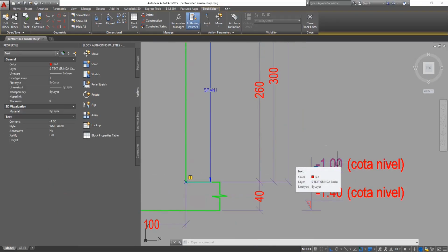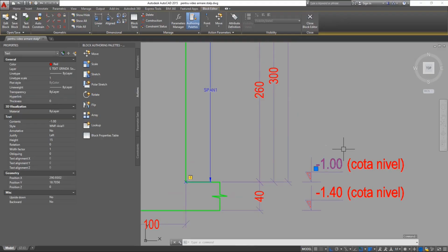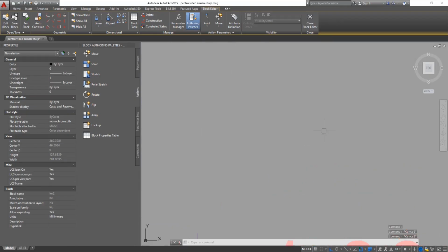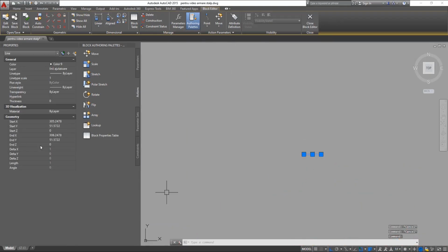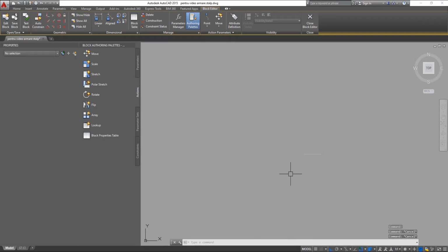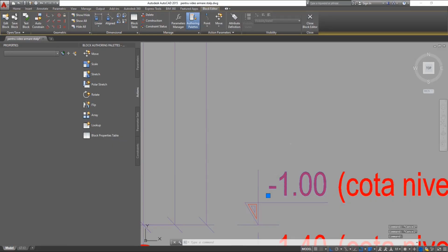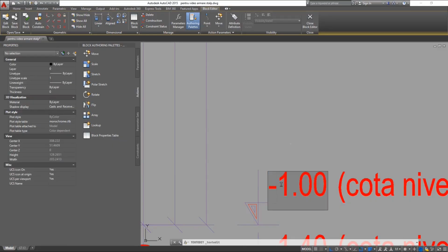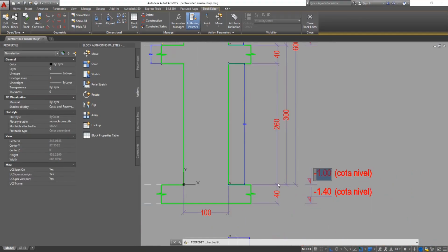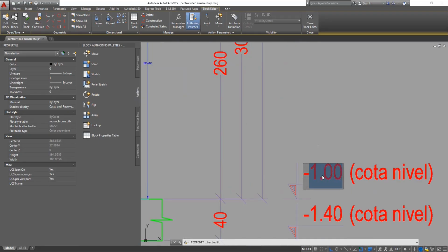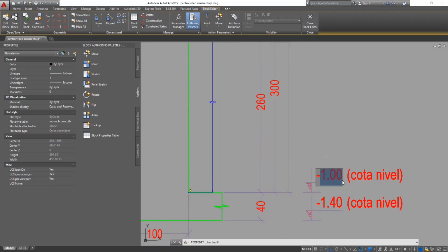So first we shall give this object a value via a field with the help of this small line, which comes by default with a length of 1, and we shall choose the number without the minus sign, taking into consideration that this will be the base of the building, which in most cases comes with a negative value, because as you know, the 0.00 level is actually for the architectural finishing of the base of the building.